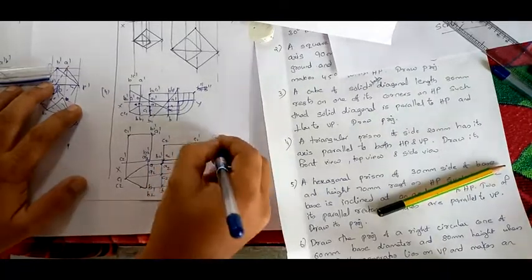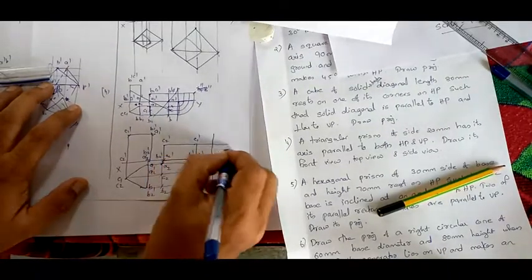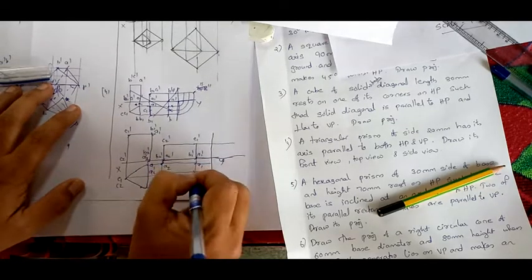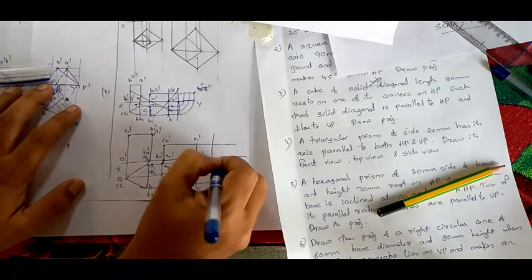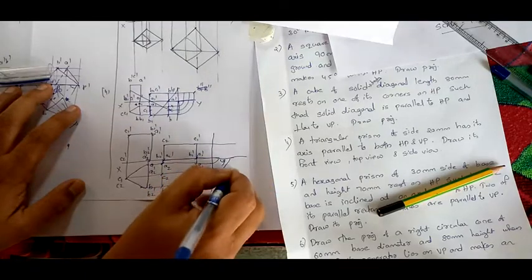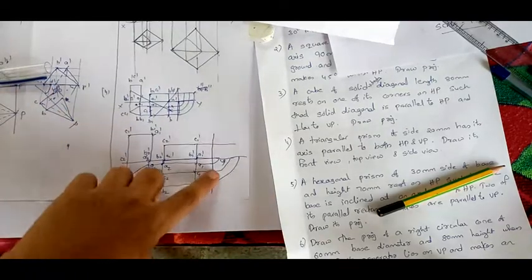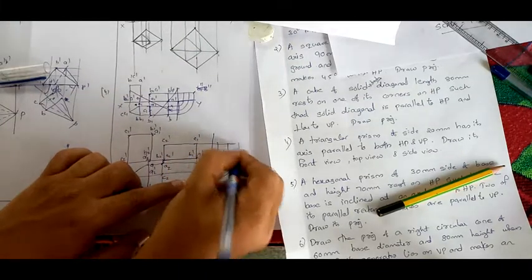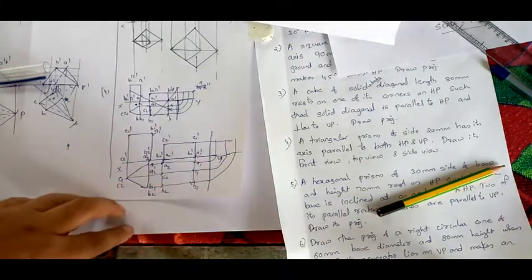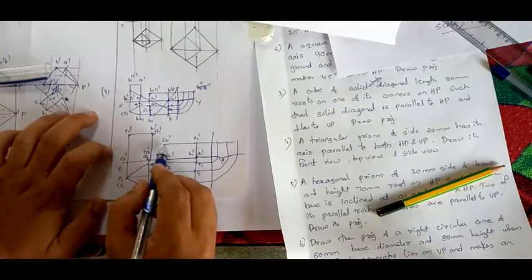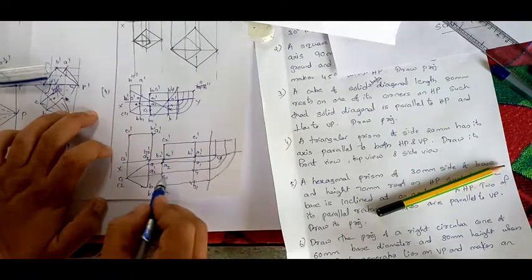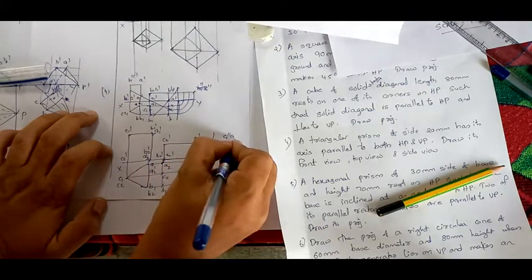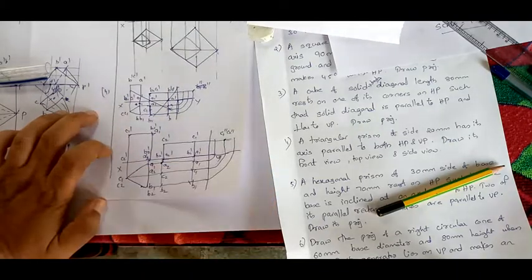Now I am constructing the side view. Listen carefully. We will project here. We will project here. Now project from here, rotate this, which we have already shown in the lines, right? And from here project upwards. Now you have obtained the view. See, C2 and C dash will be on this line. So C2 and C1 are coming here. So C1 double dash and C2 double dash will be this point.